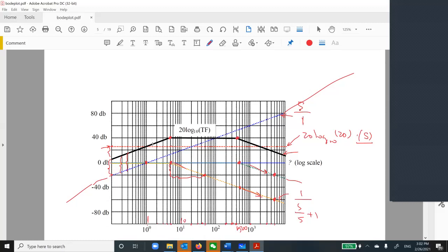So this is positive 20 dB per decade. And this black one is negative 20 dB per decade. So by doing that, you will see going up, constant, going down. What's that? It is as if you have a band pass. So I only go up and then constant and go down.